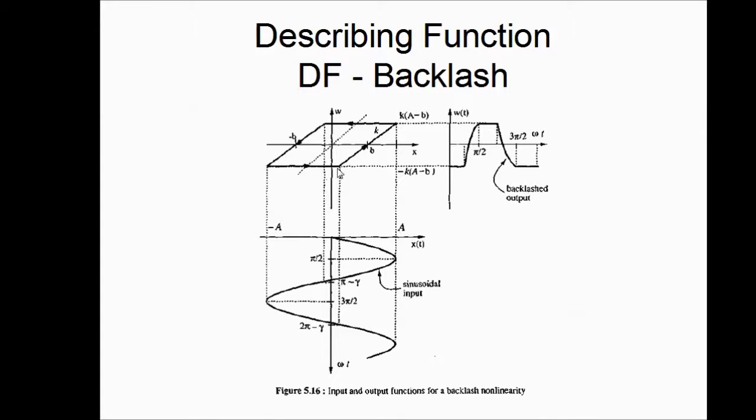That's because of the forward segment: when the sinusoid is increasing, the lower part of the hysteresis nonlinearity is active. That segment is active, and the reverse segment is inactive. When the sinusoid is going down, that is when the dynamics is from right to left, the upper segment of the hysteresis nonlinearity is active, and the lower part is inactive. It's because of this reason that the output waveform will have a phase shift as compared with the input.